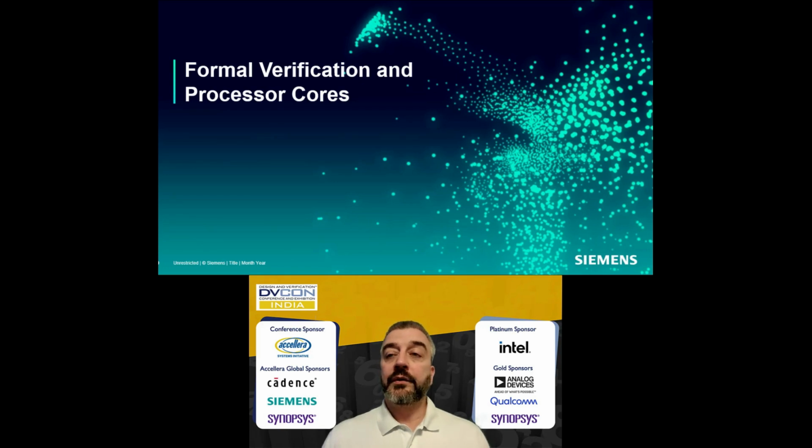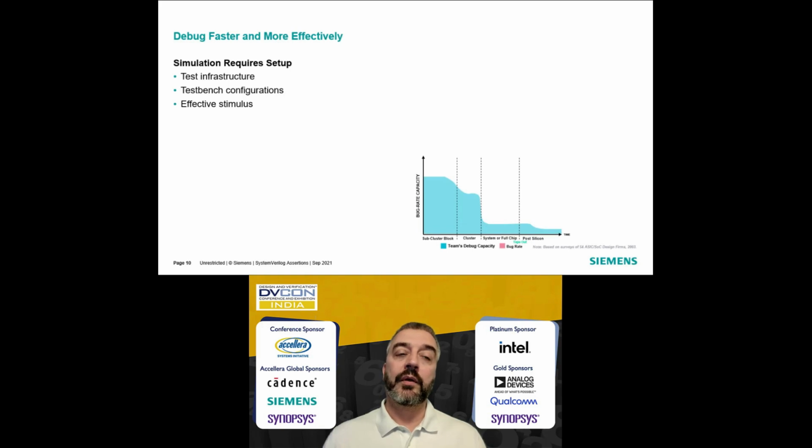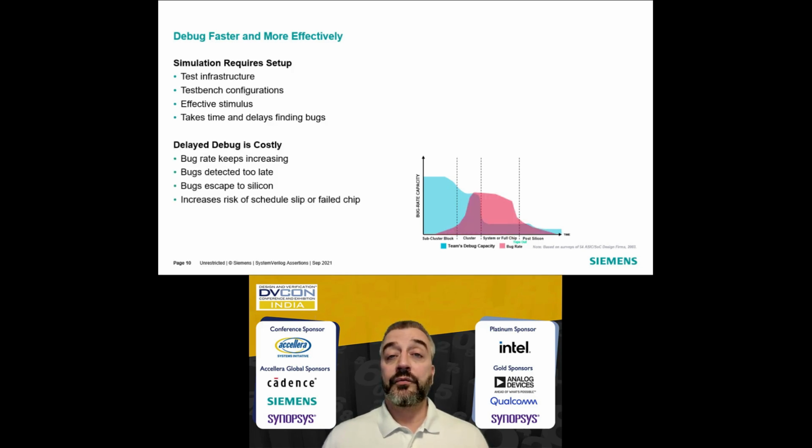So let's now look at how formal actually helps here. And first is again on the effort side of things for formal and the efficiency side. So setting up a simulation-based environment can be quite some overhead. Of course, once it's up and running, you also will be quite productive, but the initial time to get it up and running is considerable. And of course, you want to find bugs as early as possible, because as we all know, finding bugs later in the project cycle tends to be lots and lots more expensive.